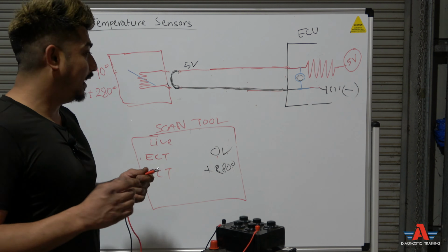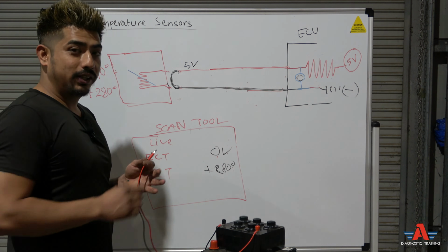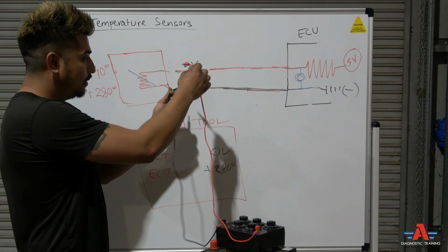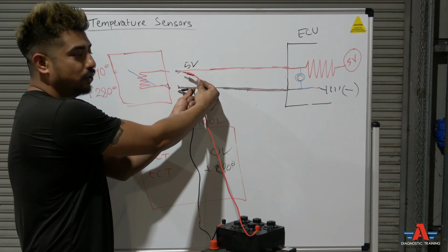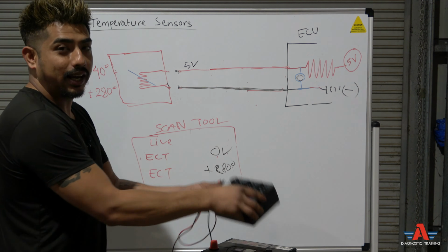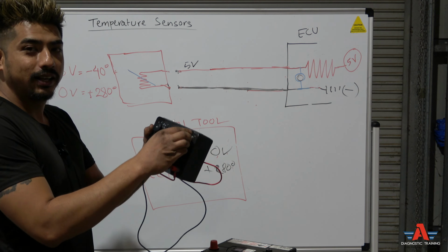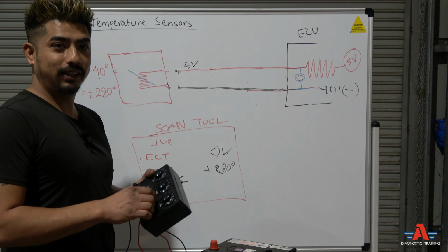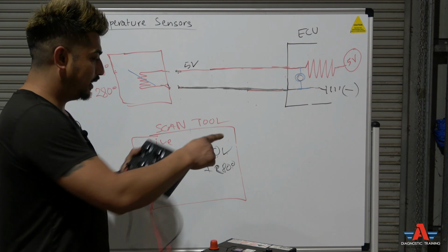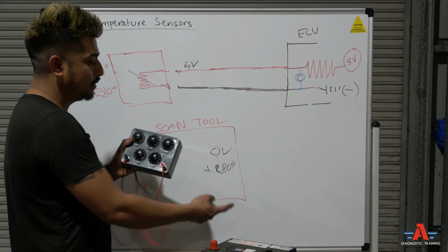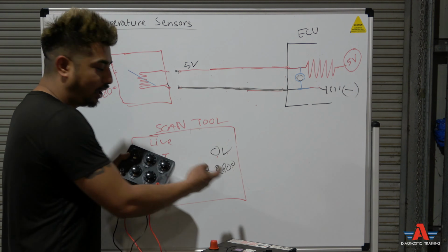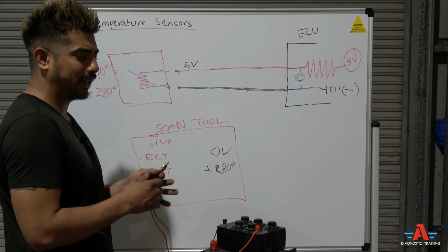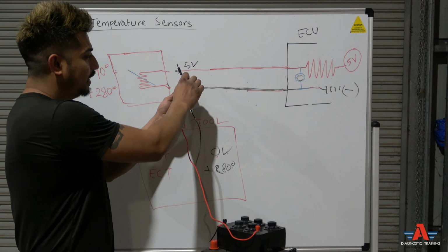So what I did the next day, I went to the coolant temperature sensor, disconnected the sensor, right? And I put a resistor in that 2-wire connector, and I was playing with the resistor. I made it read like cold, like 10 degrees, I think 20 degrees on the scan tool. As I was playing with the resistor, I was looking at the scan tool, and when I got that cold, 10, 12 degrees Celsius, whatever it was, I left the resistor like that.